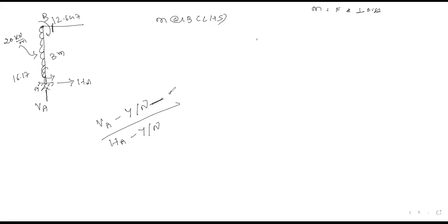No, that is right answer. Okay, because your force is available but distance is in y direction, so this distance will become parallel distance. That's the reason VA will not create any moment at B, but your H is available force in x direction and distance available in y direction, so HA will create a moment. So I hope all of you are able to understand this concept. So what is the direction of moment? Anti-clockwise or clockwise? Just rotate about point B, we will get an anti-clockwise direction.